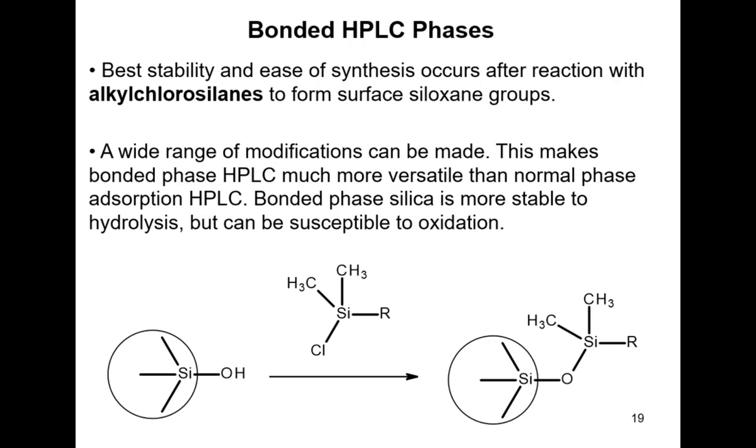We're helping to protect the silica now, so we're putting this coating around the surface, and we're protecting the silicon-oxygen network from hydrolysis processes, because if there's water getting into the system, the silica particles can slowly just dissolve in the water by hydrolysis of the silicon-oxygen chains.